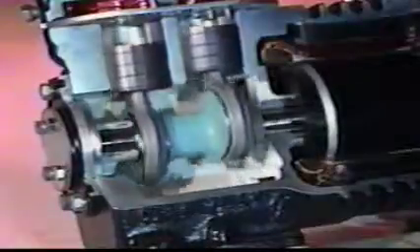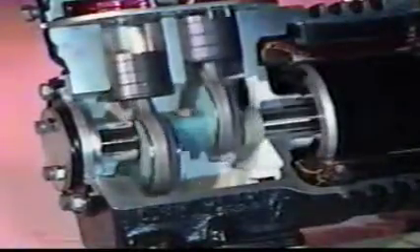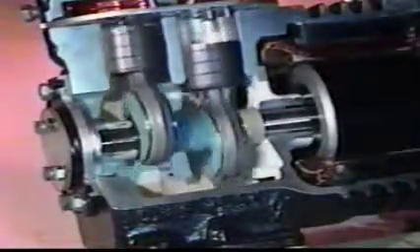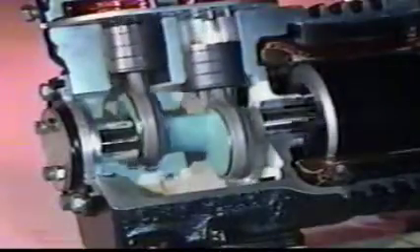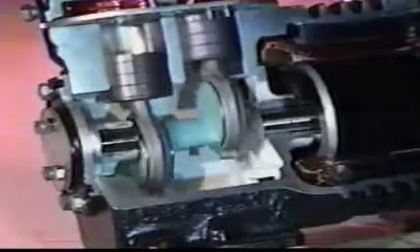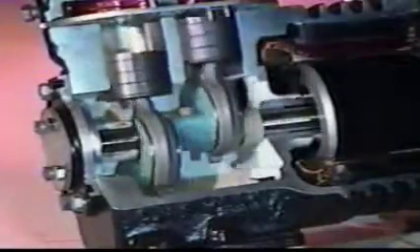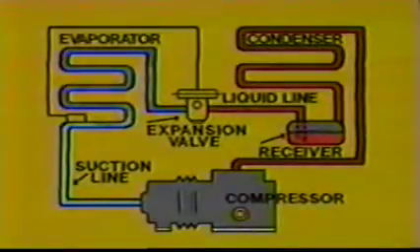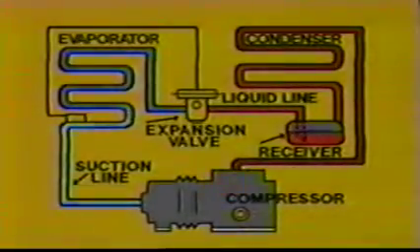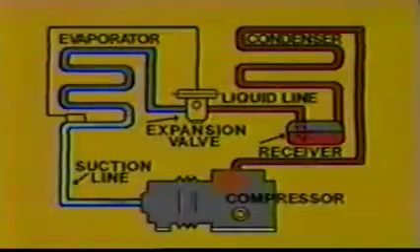The compressor is a metal factory, full of small orifices and close-fitting metal parts, many of them moving against each other. The list of ways contamination can destroy a compressor is too long to even begin. It also works the other way around. The compressor, breaking down for other reasons, can fill the system with the very contaminants that can cause even more damage to the compressor.